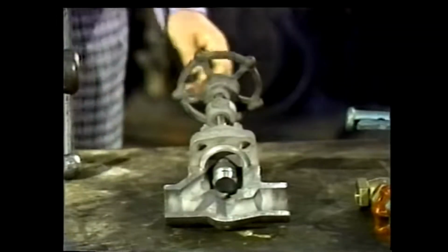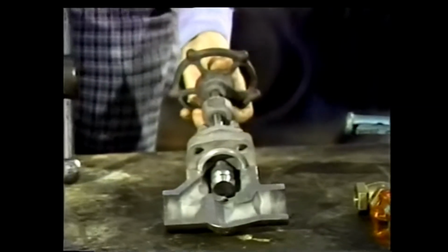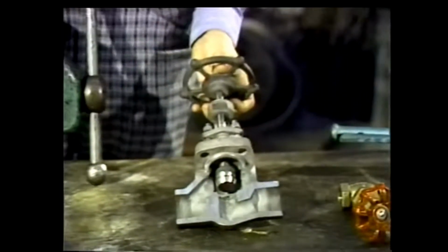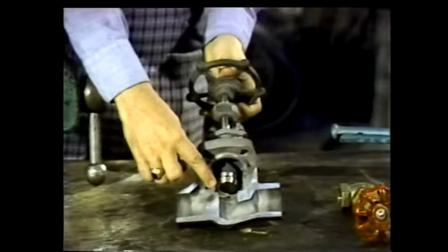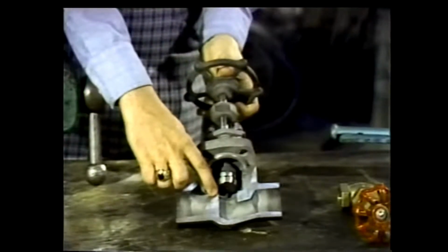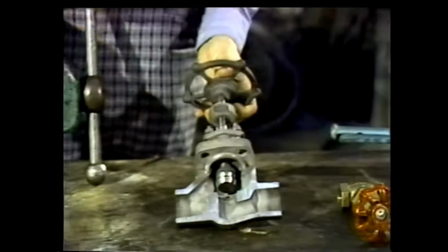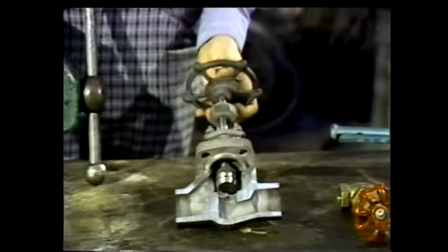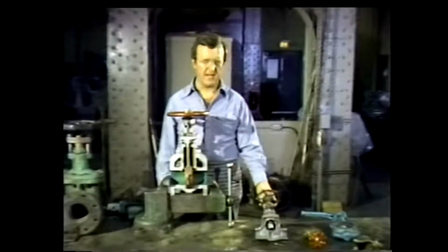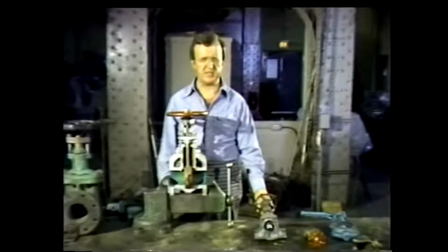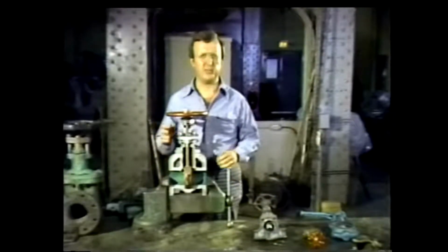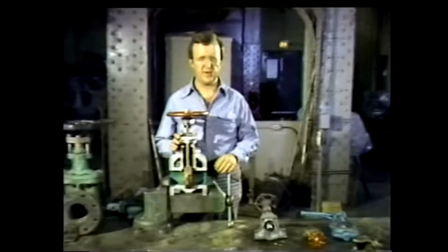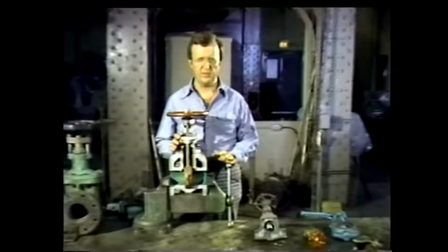The globe valve, however, can be used for regulating of flow. It's often called a control valve. The shape of the disc and the arrangement of the seating areas distinguish a regular globe valve from a control valve. By its design, the globe valve provides a tight seal where heavy-duty throttling is required, such as in a high-pressure steam system. Throttling is reducing the flow without fully stopping the flow.